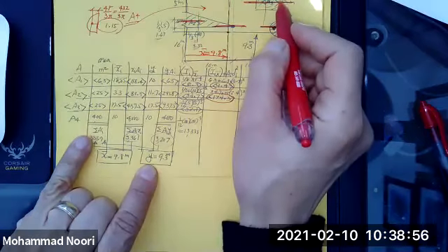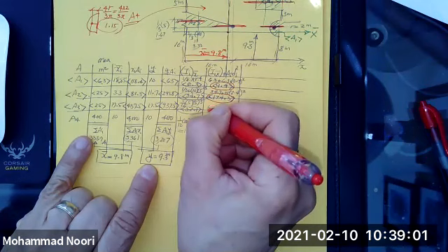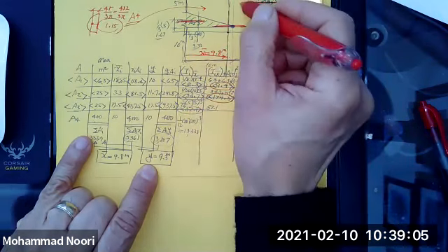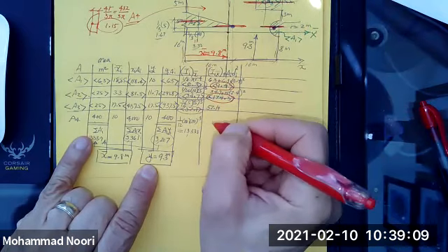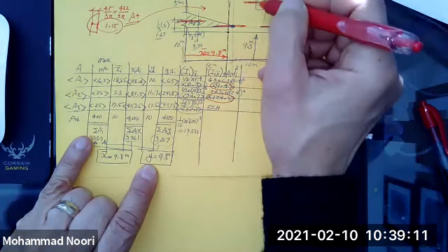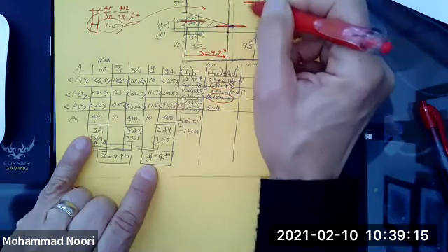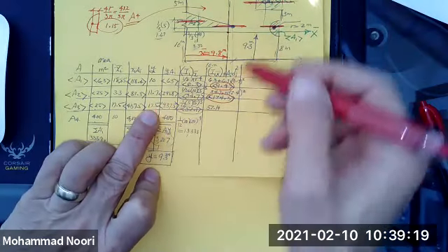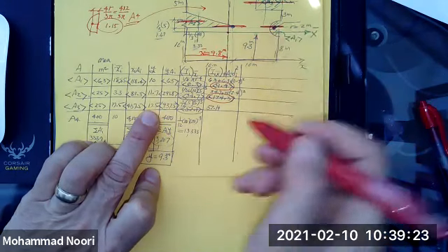So go to A3. You want, again, to add what you have here, which is the moment of inertia of this shape about its own centroidal axis, plus the area times the distance squared. This is from here to this. This was 17.5. Subtract from it 9.3, that would be 8.2.